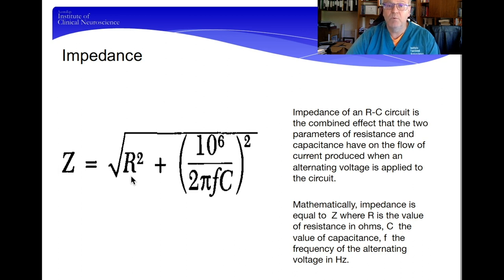Now, impedance is important when we're putting an electrode onto a substance like our skin, because we need to have a flow of electrons. We need to have a flow that's great enough to allow our current to be produced that we want to put through. So on the DC machines, and even on the EEG machines that we use, with the electrodes, we have to work within a certain impedance range so that we know that we have a conductance that is able to support our ionic flow that we want. Okay?